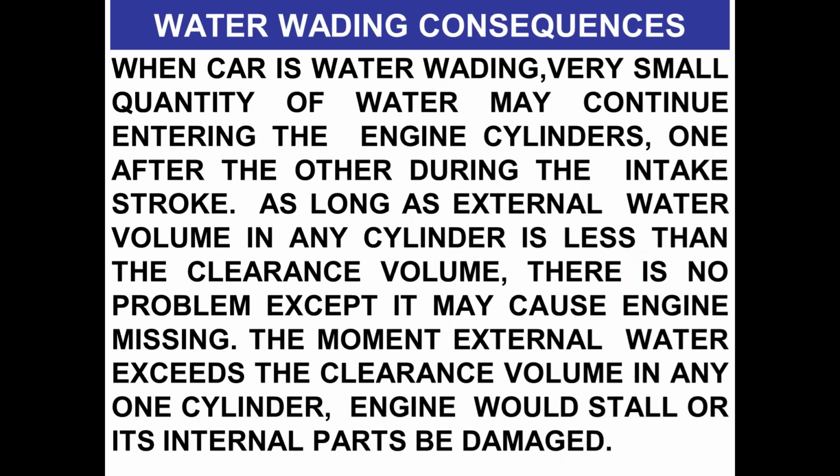Water wading consequences. When a car is water wading, a very small quantity of water may continue entering the engine cylinders, one after the other, during the intake stroke. As long as the external water volume in any cylinder is less than the clearance volume, there is no problem except it may cause engine misfiring. The moment external water exceeds the clearance volume in any one cylinder, the engine would stall or its internal parts be damaged.